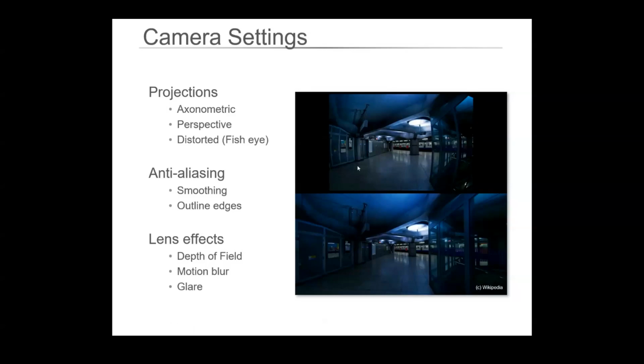And then we can think about how we want to project the view. So whether we're going to just use an axonometric view, so it's more square, looking down at say 45 or 30 degrees, or a perspective view, so we're going away to the viewpoints. We can bring in distorted views with fisheye cameras. Again, in ArchiCAD, you can set the view field on your view setting from very fine to very wide.